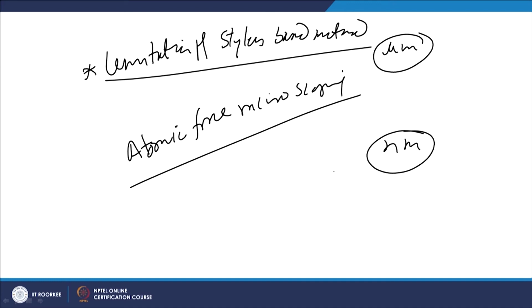This helps us measure surface roughness of very low values like 20, 30 nanometers. But for micro level surface roughnesses, simple stylus-based surface roughness measuring instruments are sufficient.